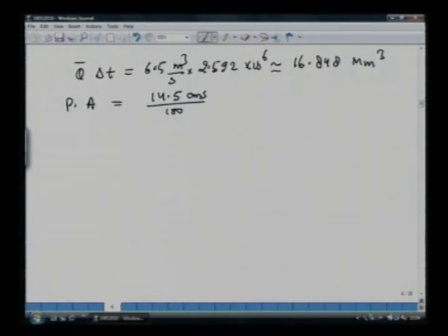So, this is the amount of precipitation that falls on the lake during the month in meters, and this we multiply by the surface area, which is 5000 hectares, a plot of 100 meters by 100 meters, and if I divide by 10 to the power 6, my answer would be in million meter cube, so that we have all the quantities in the same units.